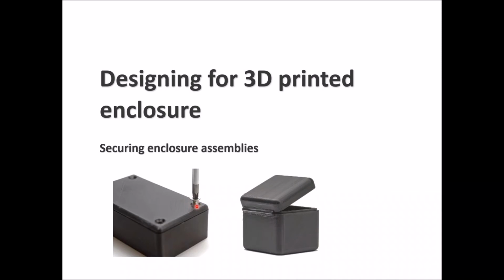Going with screws is still a very famous choice. You can see in the market all kinds of enclosures and applications and handheld devices still going with screws, all kinds and all sizes of screws, because of its plastic to metal property that will keep things in place in a cheap way. This is a living hinge. You can use your enclosure or your box to be able to open and close with a living hinge, and maybe you'll have a snap fit here to keep it closed.